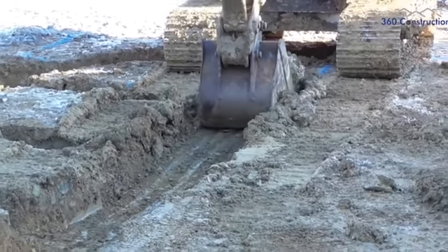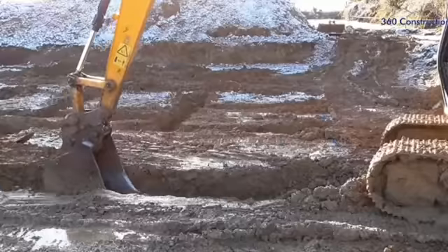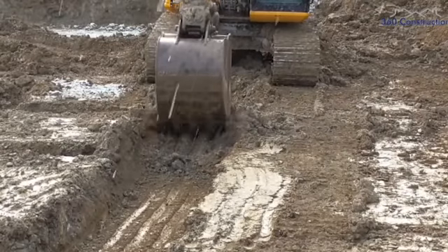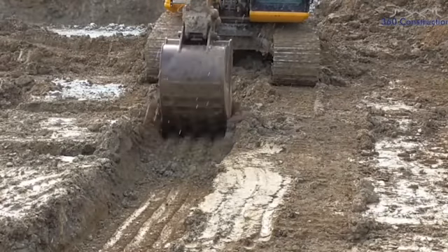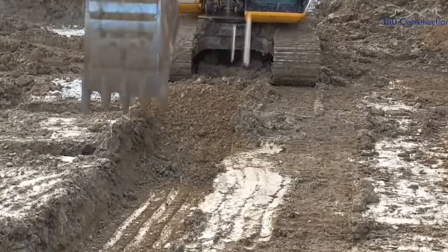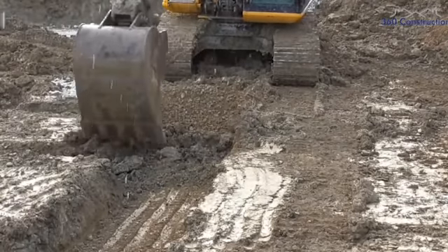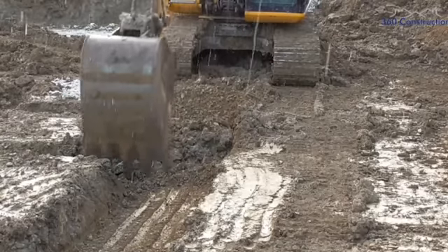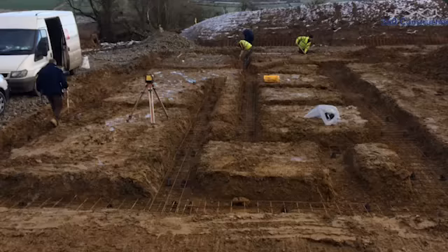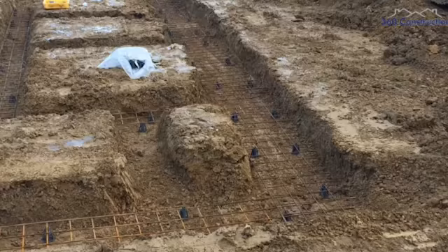Construction process of strip foundation. The construction process begins with the excavation stage, during which the specific space for the strip foundation is carefully removed. The digging depth is determined based on the structural needs and soil conditions to guarantee a solid and safe foundation. Following the excavation process, the arrangement of the foundation begins to form on the cleared site. Accurate measurements and alignment are the highest priority during this phase, as they must line up with architectural and engineering drawings. Next, the dug area is filled with steel bars, precisely placed to meet engineering criteria.